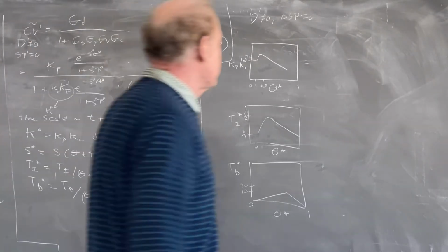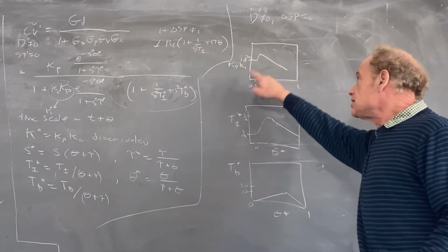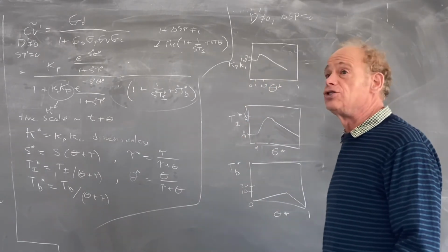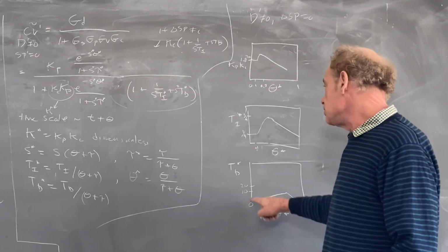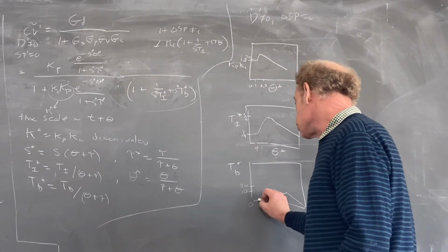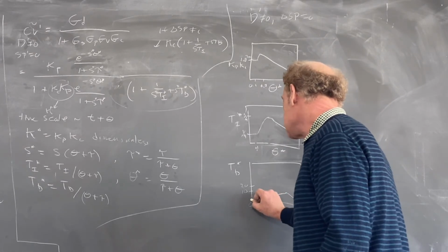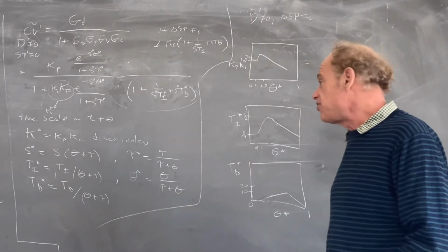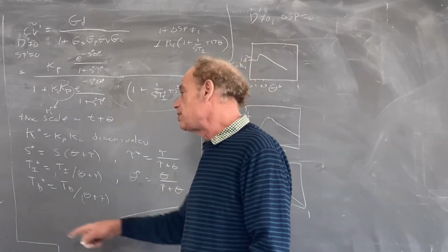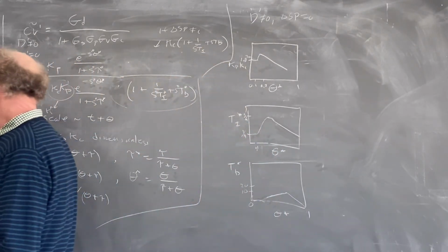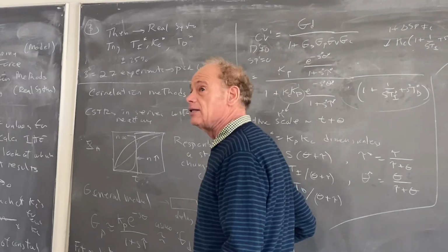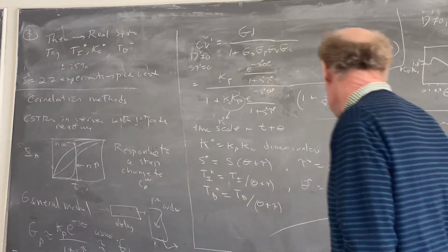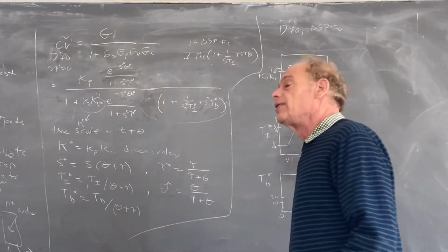Okay, so first let's look at the beginning part. Notice the beginning part, until I'm about 0.1, KC doesn't change, TI doesn't change, and TD is effectively 0. It doesn't really start until later. So what does that mean? That says if the delay is effectively 0, I do a change to the system, I see it immediately in the output. Then I don't need to anticipate, because I see the results immediately. So TD is 0. I don't need to anticipate.